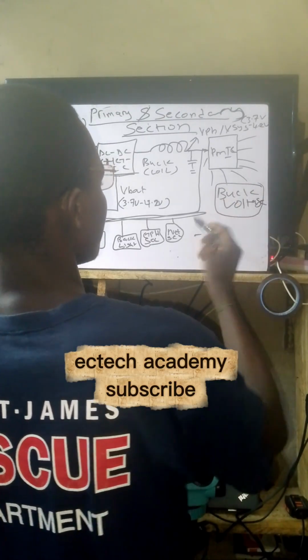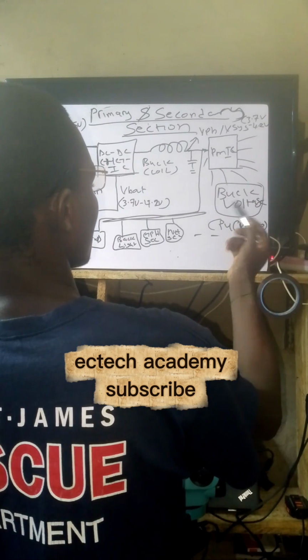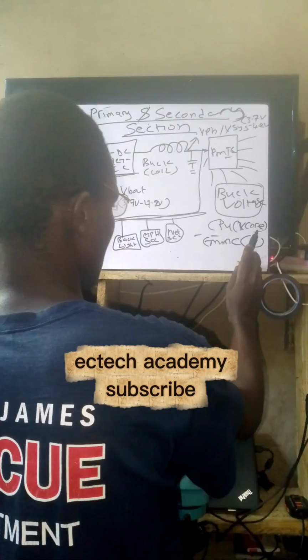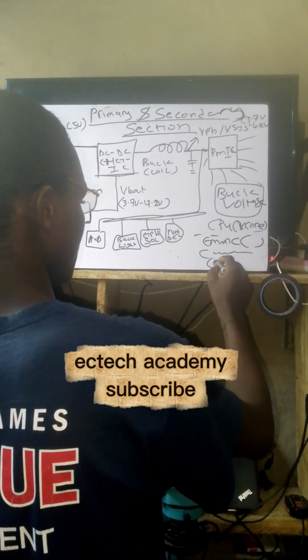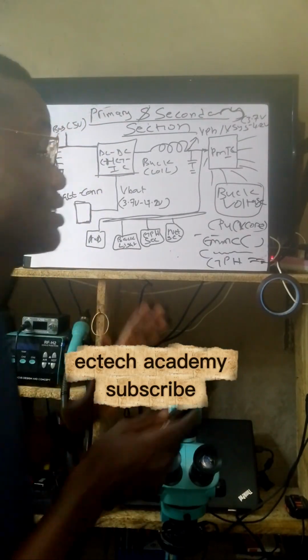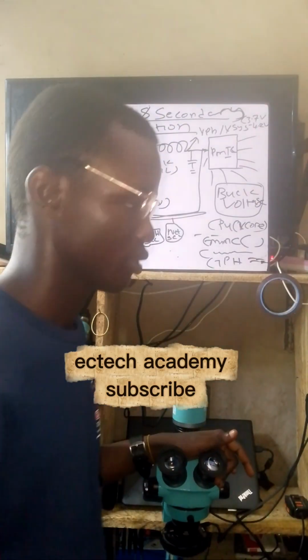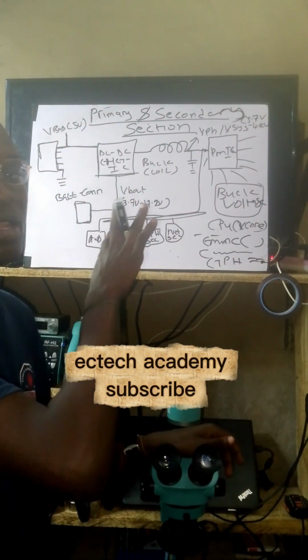So among the buck voltages is the voltage that goes to the CPU, which is VCore. We have voltage that goes to eMMC, that's your flash memory. Then there's a voltage that goes to the camera section, to the graphics section, and many other sections like that. So that's the output voltage coming from the power IC. It's a power management IC, the one that supplies voltage. So now this is the diagram of the mobile PCB.